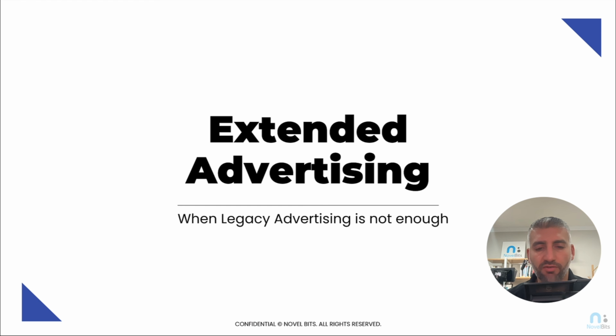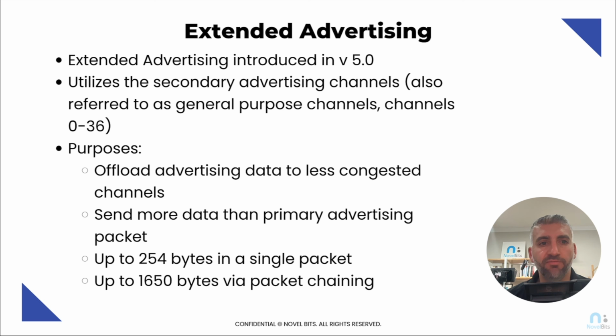So, extended advertising. I like to say that when legacy advertising is not enough, then you use extended advertising. And this is why. Extended advertising was actually introduced back in 2016 in version 5.0. And it allows you to use the secondary advertising channels, or what were commonly used before that as the data channels.